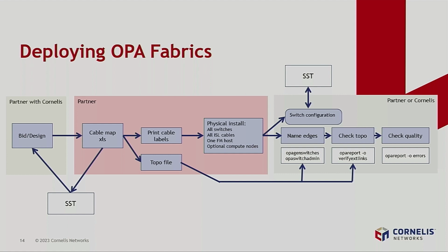So currently you can generate the proposed design, feed that into SST, run a simulation, change some parameters in your software stack, such as adaptive routing thresholds and QoS, and then you can see how it improves, or how it doesn't improve. That should give us a fairly good baseline for when the hardware hits the floor, that we think your configuration for your fabric manager should be this, and then we should be able to plug it together.